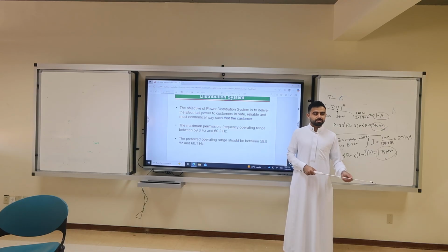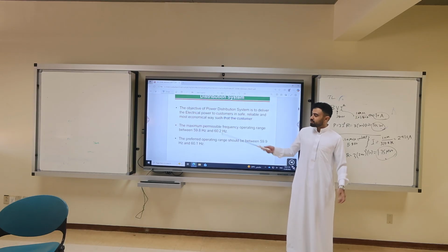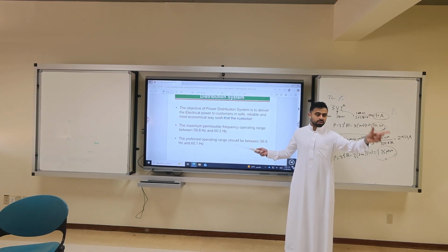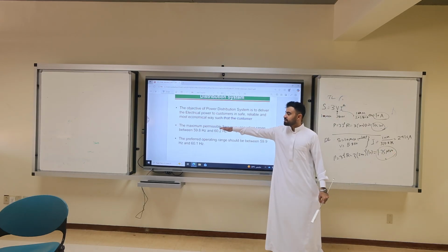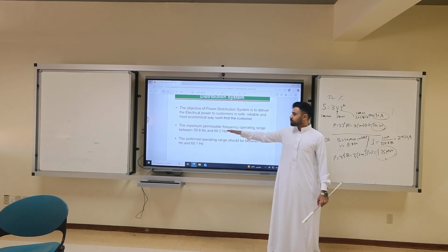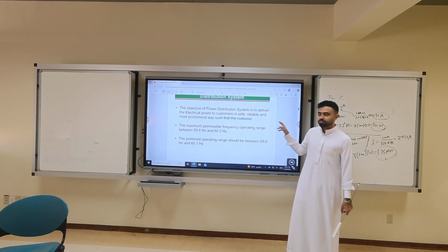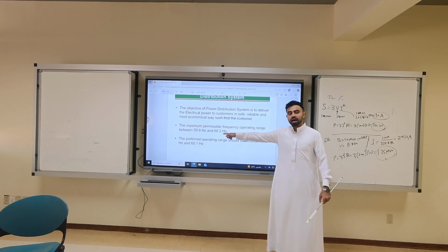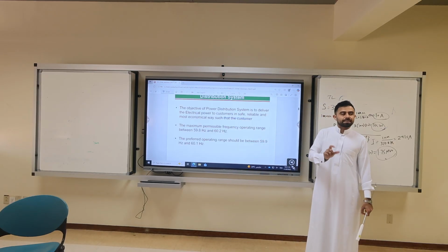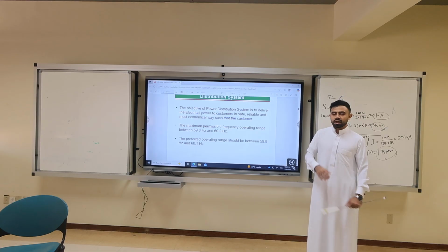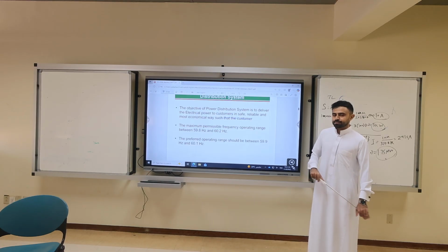Ahmed? 60.2 minus 59.8 is a 0.4 range. This is a 0.2 range. This is preferred. This is permissible. Permissible means 60.3 is not allowed. 60.2 is allowed but not preferred. And you can operate there for a period of time, but you can't rely on it.